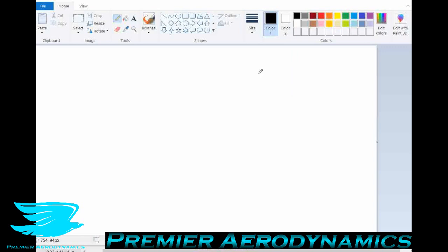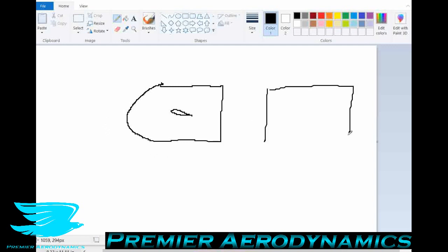So this C-grid topology, if we have a typical CFD box, then we have the front, this curve, so it's a C. Then we have the airfoil inside. And the reason why this C inlet is quite important is because if we were to have just a regular flat box, like a flat front, a square front, then if we wanted to change the angle of attack of the airfoil, we then need to literally change the geometry.